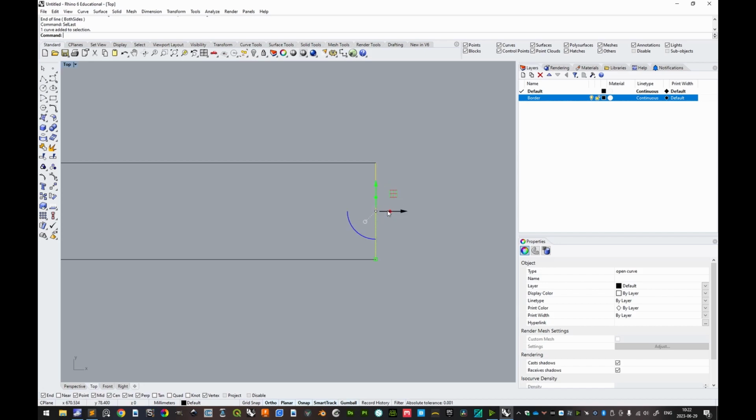Very good. And in this case, I want to make sure the edge of the border here should be 43 millimeters to the inside of that. So in this case, since you see that the red arrow points here to the right in the view, if we click this arrow and type -43, it will move the objects in the negative direction, so to say, as you see, to the left. Very good. And this can be in a new layer, so I'll click the new layer button there, and this can be called inner border.